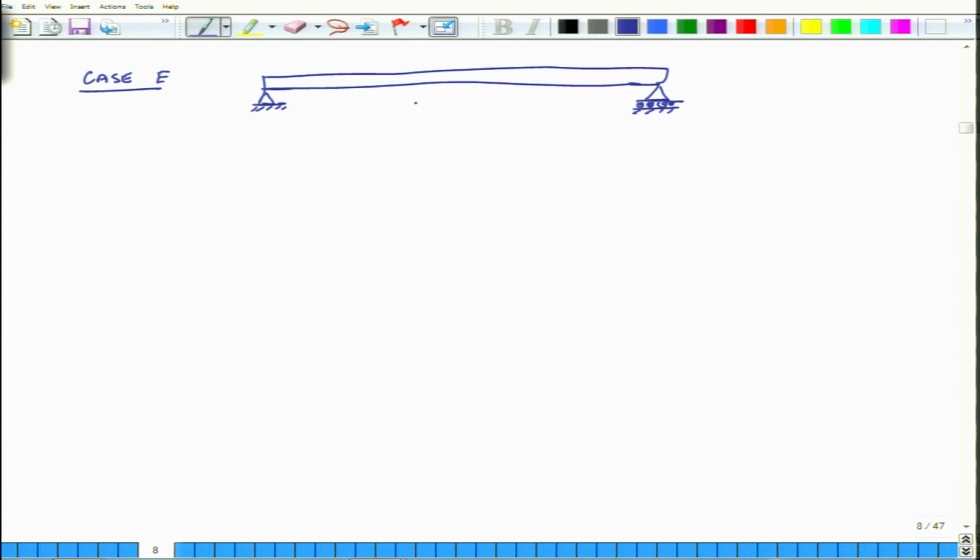The lamination sequence of the plate is 0/90. So, the 0 layer is on the top, and then we have the 90 layer on the bottom, and then this plate is being subjected to Nx at this edge. So, I am pulling this plate, and let us say that the value of this tensile force resultant is N bar.